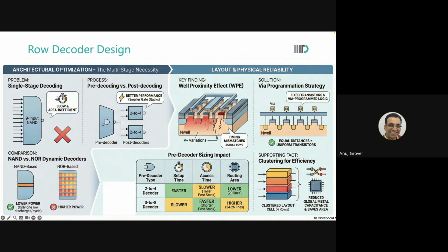Are you able to see this? So what you say is that, okay, instead of using four NAND gates, which have exactly the same inputs and exactly the same output, I will instead use one NAND gate. Again, let the 0 come there, and it will go as an input to all the four of them. I have reduced 3 extra NAND gates in this setting. So in this setting, you are actually using only the bits 4 and 3. No, I'm using 5, 6, 7 also.